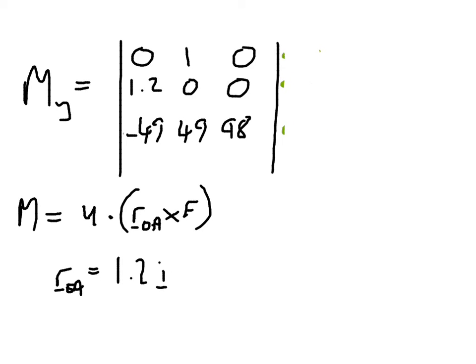So we've got a force acting in a direction. It's starting at a point relative to the origin, and we want to know what turning effect it has along an axis defined by this unit vector. So we'll do the cross product of the bottom 2 lines and then multiply by the top line.